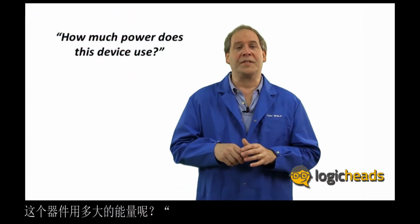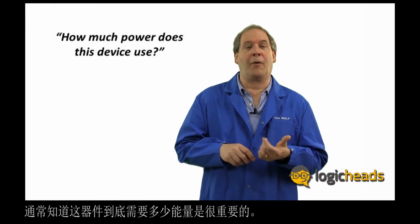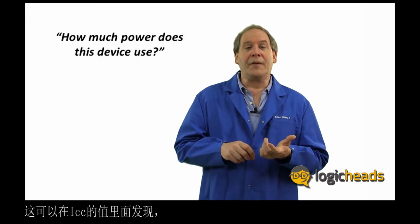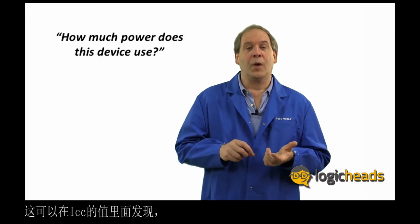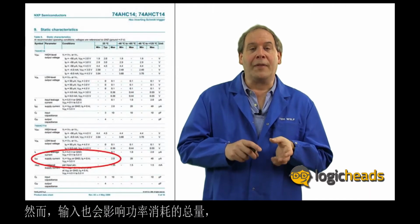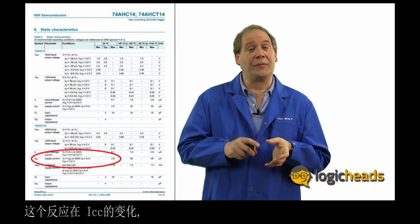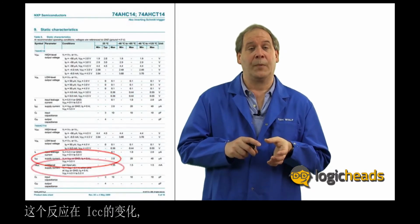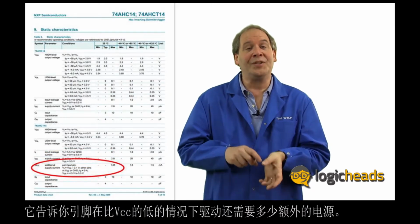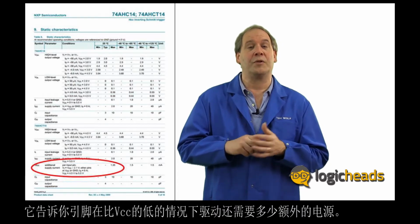How much power does this device use? Often it's important to know exactly how much power a device will use. This can be found from the values of ICC, which is the base amount of current that the device needs. However, the inputs also impact the total amount of power consumed, and this is reflected in the delta ICC, which tells you how much additional power is needed if an input pin is driven lower than VCC, your supply rail.